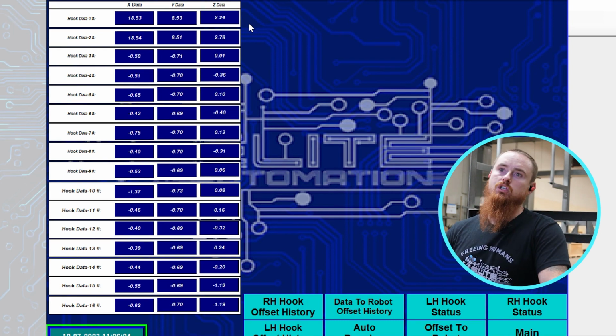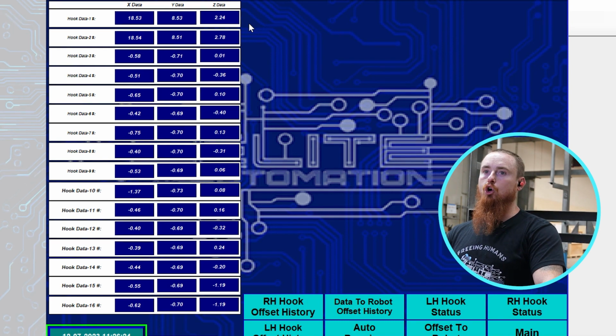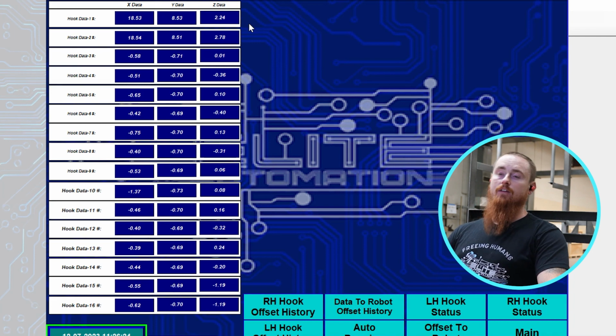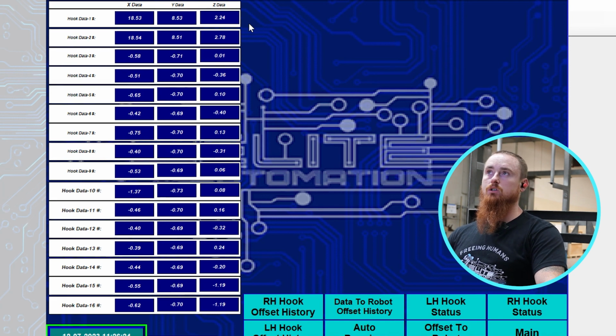inspections. Now I will say I think that these tolerances are low as of right now. These tolerances can be cranked back up. So this is a bent hook. I can tell from this data, this negative 6.72 is definitely a bent hook. That data is too much, whereas I think this 2.3 is still acceptable data. We just have our tolerances set super low.